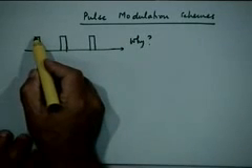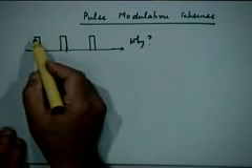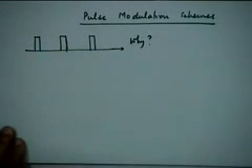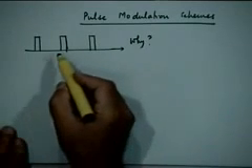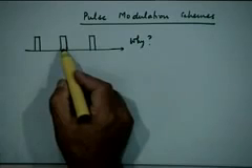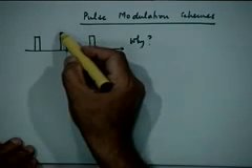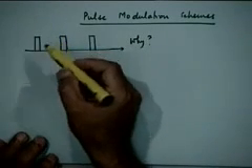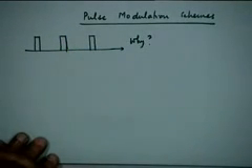You're multiplexing a lot of information by transmitting each information in a small interval of time. So during this pulse interval, let's say you measure the value of that parameter, modify its amplitude and transmit a pulse of a certain amplitude. After some time you come back to the same parameter, you remeasure it, maybe the value has changed, so you represent it by a pulse of a different amplitude and transmit that.